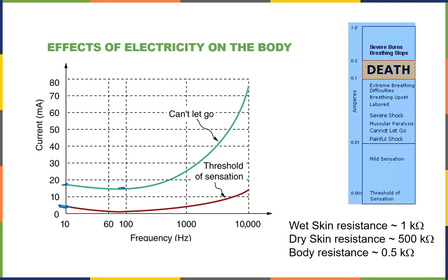And this here is just a general rule of thumb for where death occurs from, I said, around 60 to 70 milliamps across the heart. This is rounding that to 100 milliamps up to 200 milliamps. That's the range where the heart's going to go into fibrillations. Above that, you stop the heart and it's safer. So it doesn't make sense that more current can be safer than that, but it is.